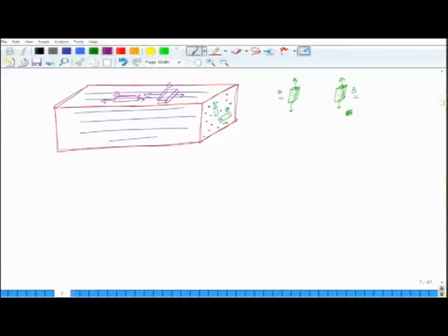The length of sample C and sample D lies in the plane, is aligned in the plane. So, this line is, at all points of this line, equidistant from the top surface of the block. Same thing is true for D. So, I am cutting the samples. Again, if you look at sample C and sample D, even though they are cut in different directions, their tensile properties will be the same.